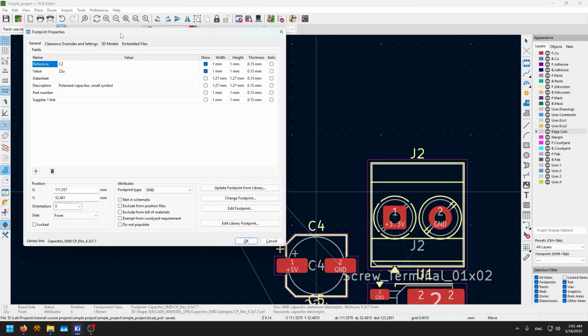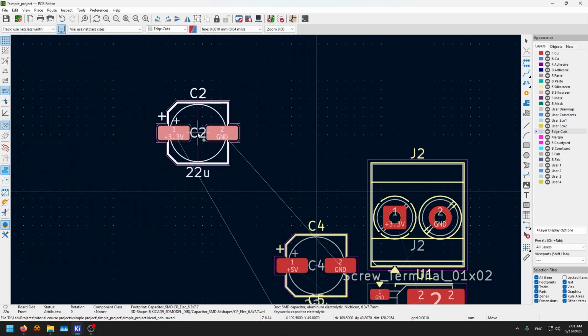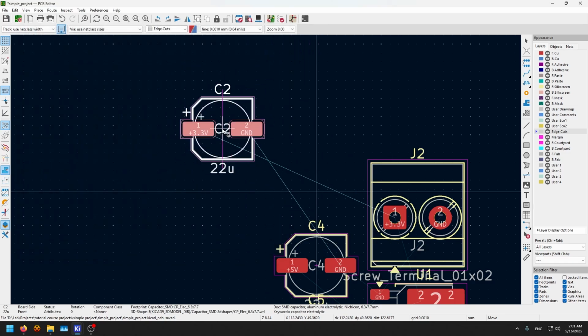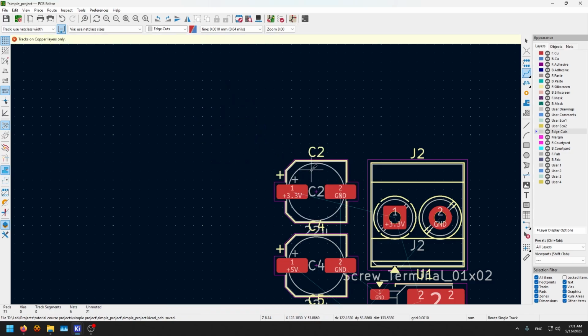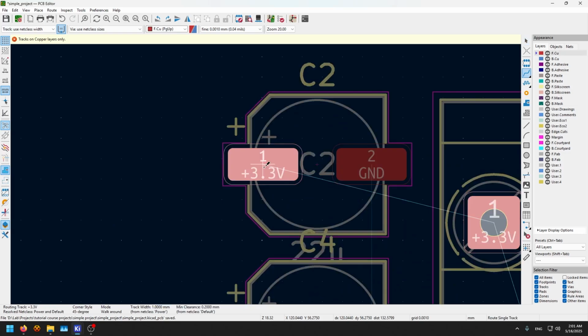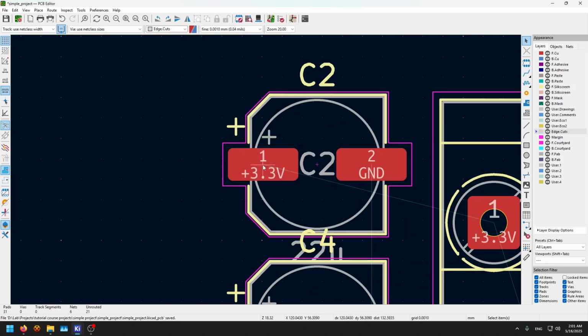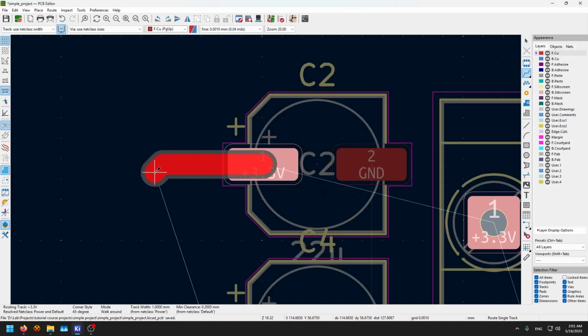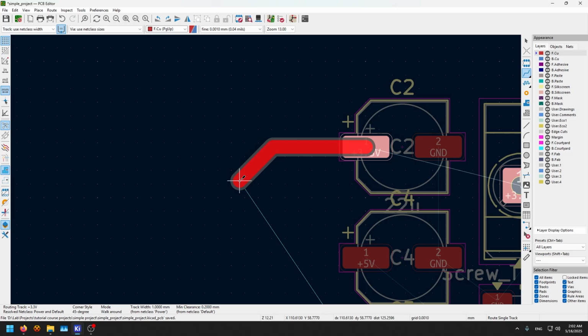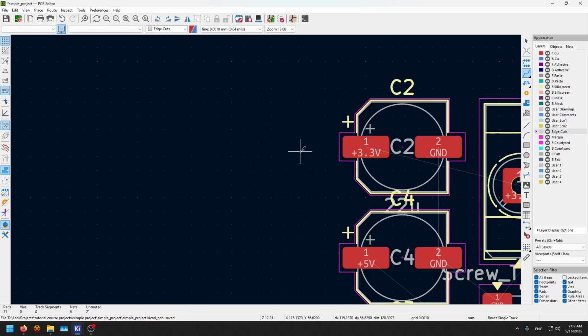Let's go to the properties of this thing, and maybe we can edit it in here. You're gonna have something like R to rotate, X and Y. No, X for routing. I'm gonna select this pad or hover over it, and I'm gonna say X. It's gonna route, and notice that once the track is out, I'm gonna press E again, and I can basically make it 0.2, make it 1, make it whatever.